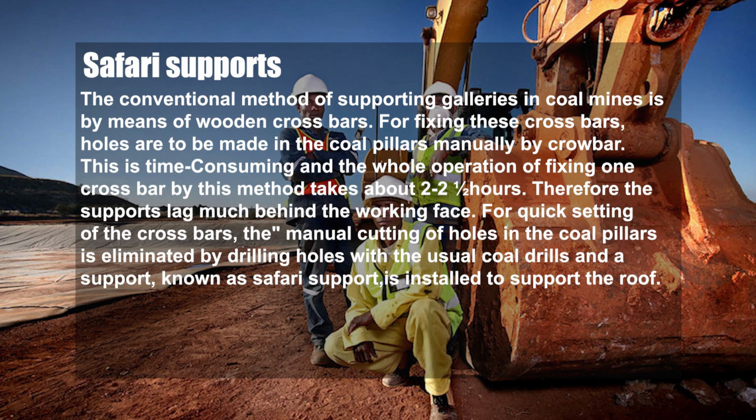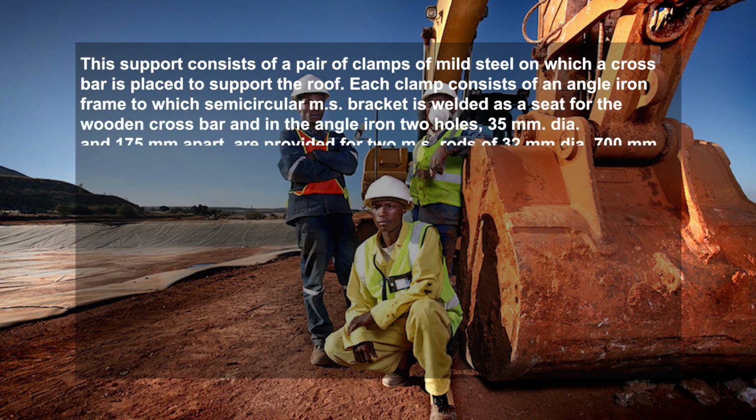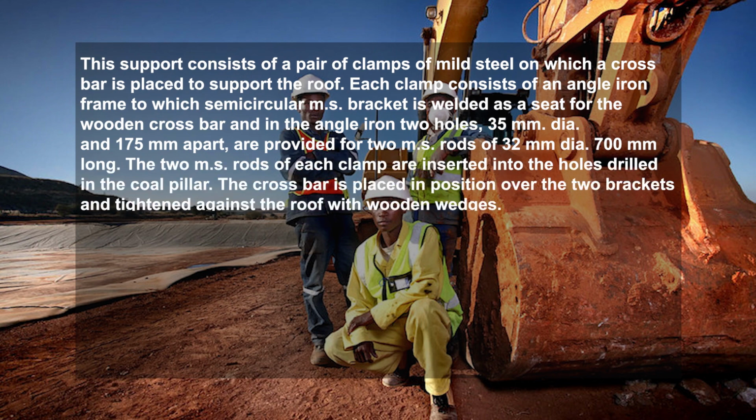For quick setting of the crossbar, the manual cutting of holes in the coal pillars is eliminated by drilling holes with the usual coal drill, and a support known as safari support is installed to support the roof. This support consists of a pair of clamps of mild steel on which a crossbar is placed to support the roof. Each clamp consists of an angle iron frame to which semicircular brackets are welded as a seat for the wooden crossbar,